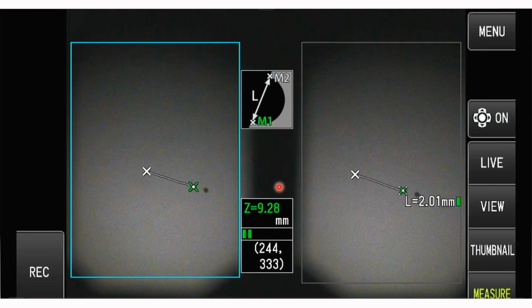So this check, which takes really 30 seconds to do, can make or break your measurements. So always, before starting a measurement, do a check of your videoscope. All videoscopes that do measurements should have these reference tests, these reference procedures.